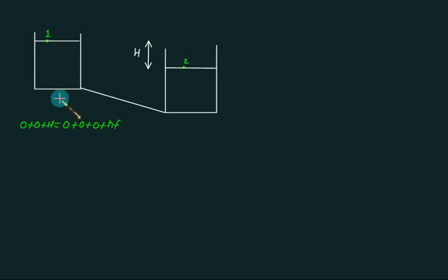Now this one is my one pipe, and exactly parallel somewhere here I have a second pipe. In the view you can't visualize that. I will say that this pipe is parallel to the first pipe. So for this pipe also, points 1 and 2 are the same, and the losses are the same. And if we have a third pipe like this, actually they are at the same level. It's very difficult to show this third pipe. Are these three pipes parallel? For all these three pipes, the losses are the same.